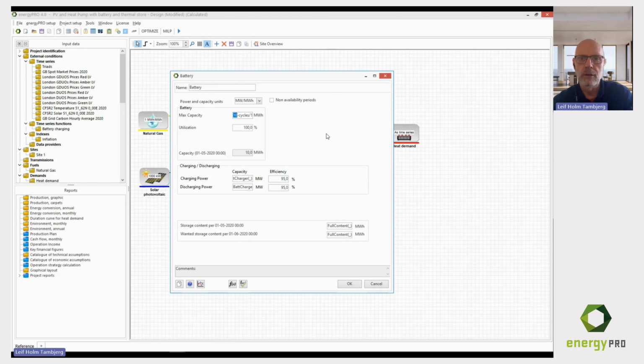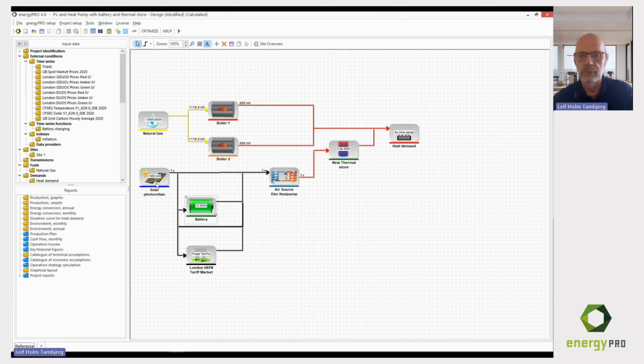That was not that complicated, but now you are able to do more dynamic charging and discharging capacities. In this way, you can also define periods where you want to charge and periods where you don't want to charge. You can say that I only want to charge the battery if, like in this case, my PV is producing, or I only want to discharge during daytime and charge during nighttime.